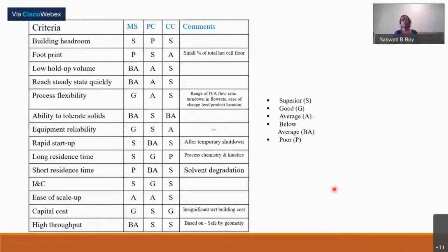There are some radioactivity points where, when it comes in contact with the solvent, the solvent gets degraded. So we have to reduce the residence time. For reducing that, we need some special aids. Centrifugal force is much higher than gravity force. So in the centrifugal contactors, centrifugal force is being used for mixing and also for settling. These centrifugal contactors can be staged contactors, or they can be differential contactors like columns. So depending on your design, you can make it.